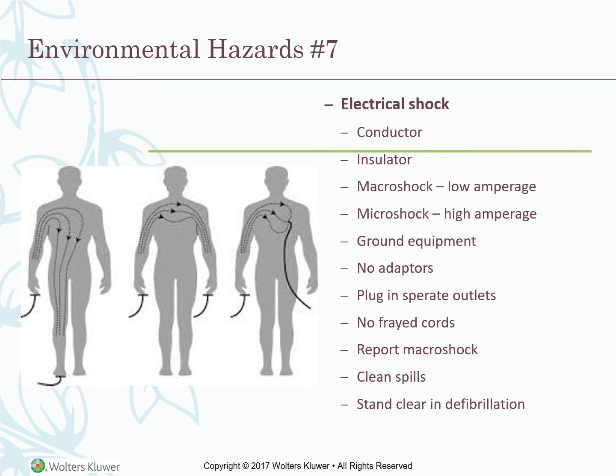Never use an adapter to bypass a grounded outlet. Make sure all outlets and switches have cover plates. Plug all machines used for client care into outlets within 12 feet of one another or within the same cluster of wall outlets. Unplug machines if they are no longer necessary.